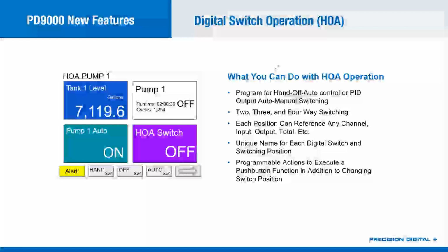So I could put 3 input channels showing tank level or temperatures or gas detection levels. And then I could also choose to put on there things without bar graphs and have alarm statuses and pump or relay run times and cycle counts and statuses of those relays, is it on or off. Those things obviously wouldn't need bar graphs, but I could put them on that channel anyway. And I would see my 8 numeric pieces of information and then the 3 bar graphs next to that.